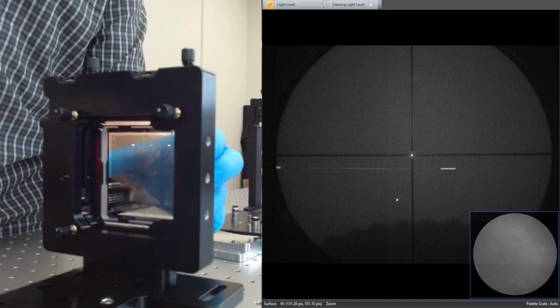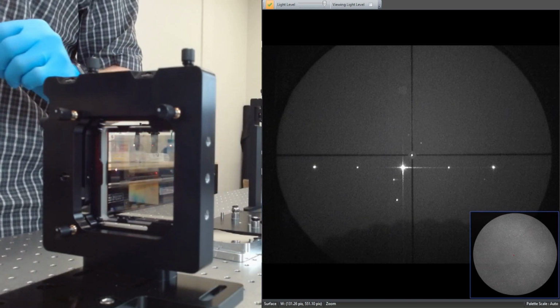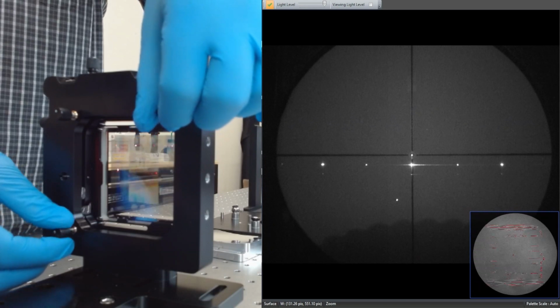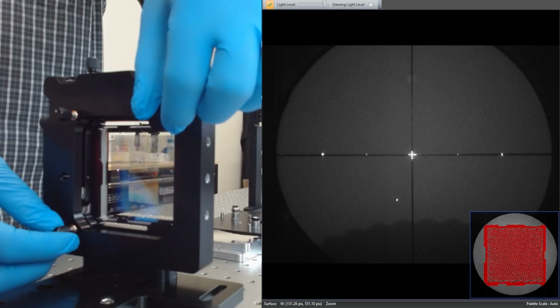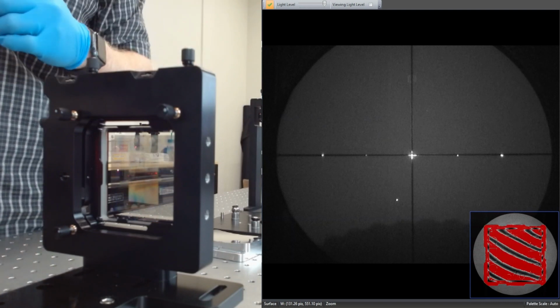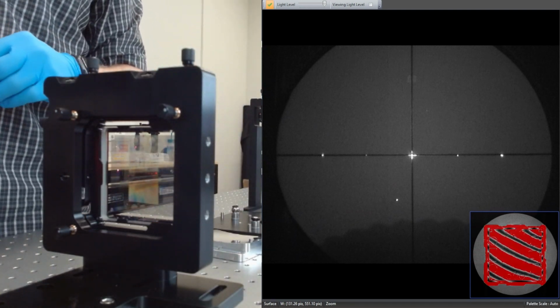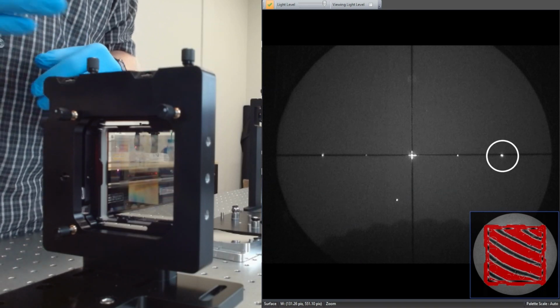While in align mode, adjust tip and tilt of the CGH until the return spots from the diffraction orders are visible. Locate the brightest return spot. This is the 0th order reflection from the planar glass surface itself. In this case, the design of the CGH indicates that the side of the CGH with the AOM logo should be tilted away from the interferometer, approximately 1 degree from the 0th order. In this case, it's the 2nd spot from the 0 order.